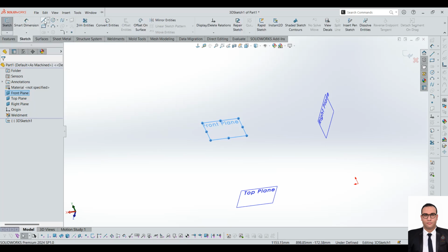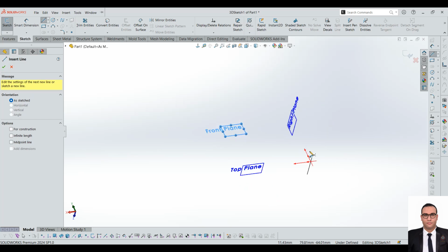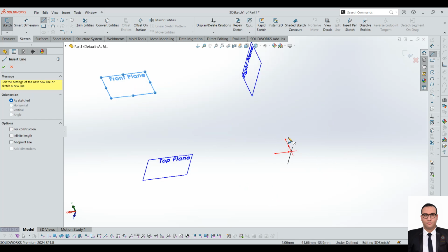I'm going to show you now an example. Let's select a line, and as you see, there is a difference here. We didn't select a plane, and we have those two red flashes here. And as we see here, now we are working on the XY plane. If we press the Tab key, the two red flashes switch to the Y and Z plane. And if we press one more time, we will have the XZ plane. So we can change between them as desired.